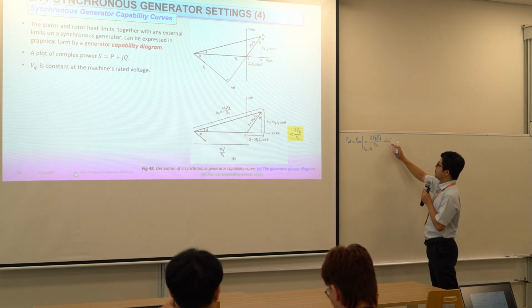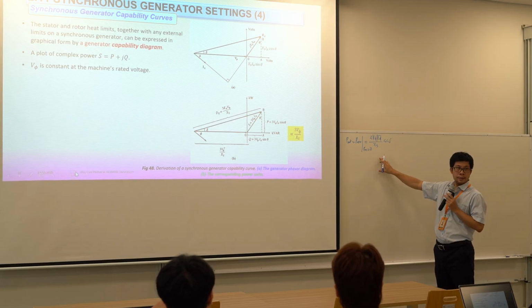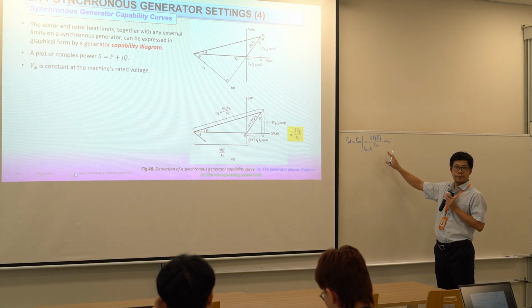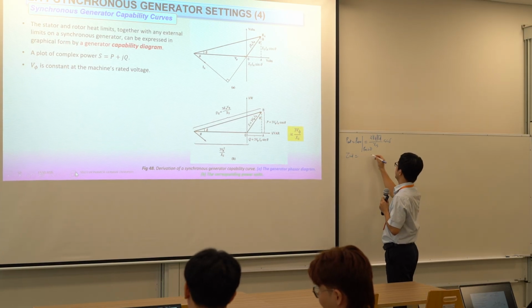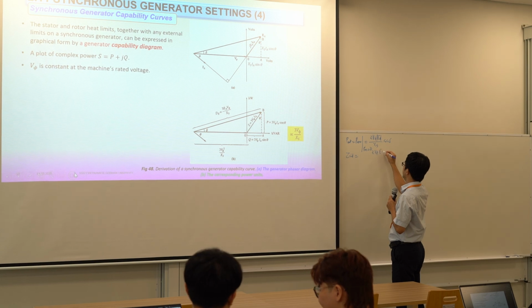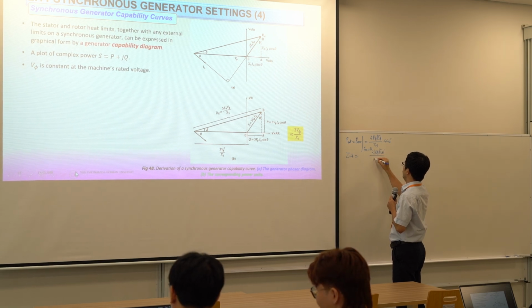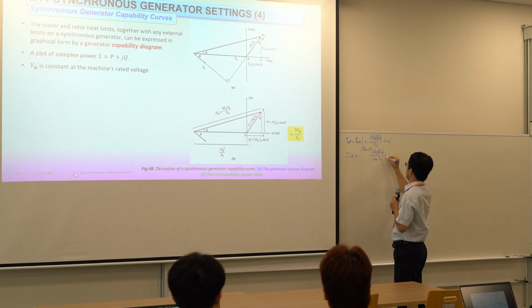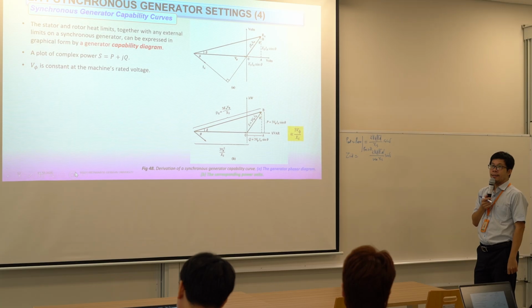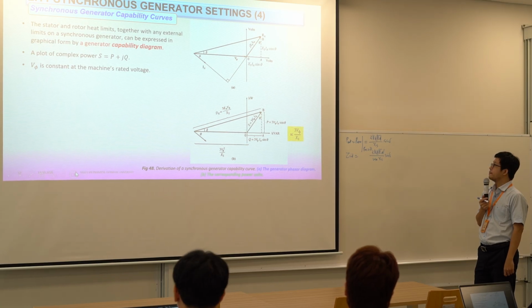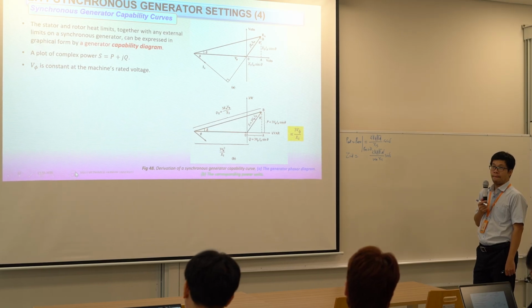Do you remember this formula? So we have induced torque like this: 3V phase EA over omega m XS sine delta.